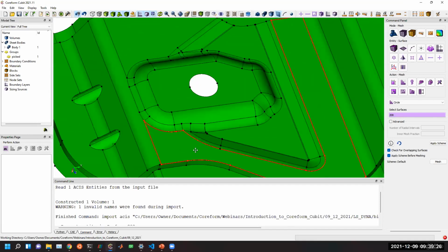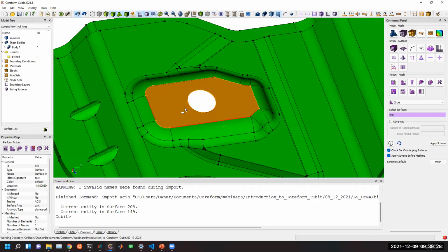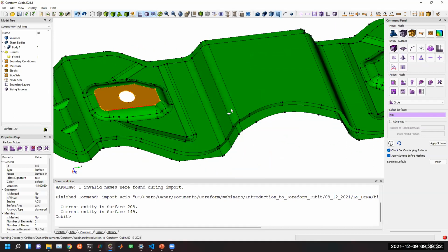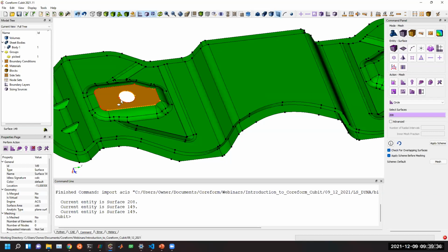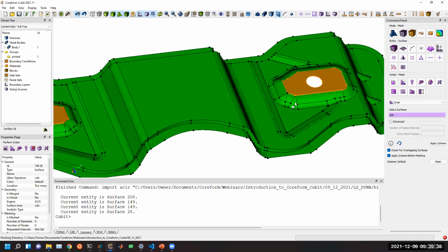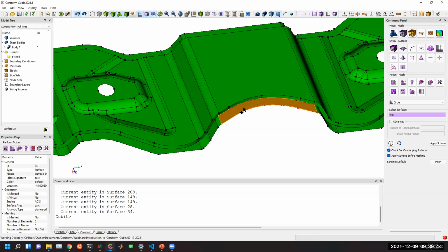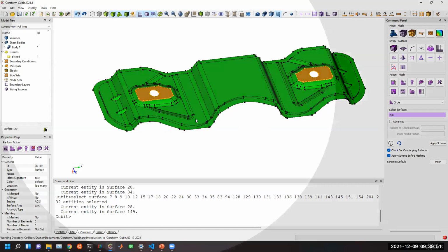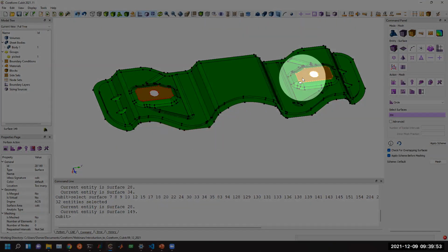And what we might want to do is run a contact simulation. But if you wanted to apply a boundary condition, maybe to these faces, you have to have them creased around their boundaries. So I'm going to pretend that for this model, we're going to effectively hold a boundary condition on this highlighted surface, and then we're going to push on these 2 surfaces that you see here.